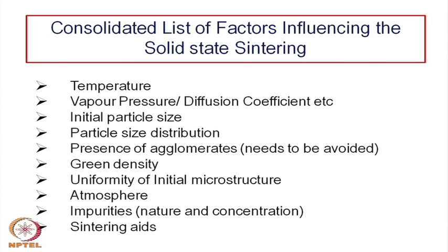Both impurities and sintering aids have more or less similar characteristics. Either they enhance the diffusion coefficient, or increase or reduce the vapor pressure, or sometimes they form liquids. So, all of them do have a significant effect on the sintering process.